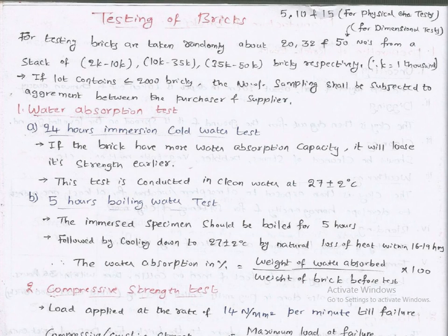Water absorption in percent is the weight of water absorbed upon the weight of brick before test, into 100.